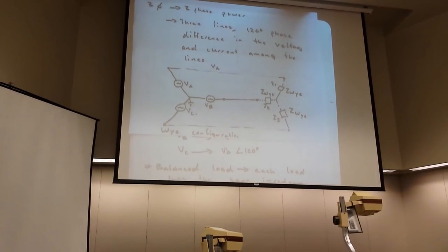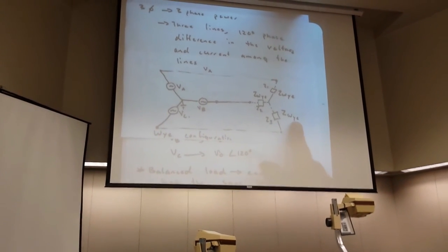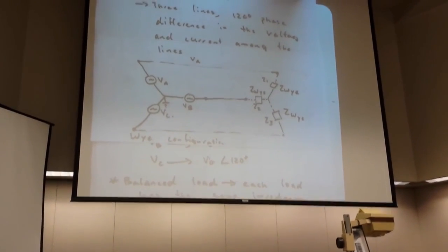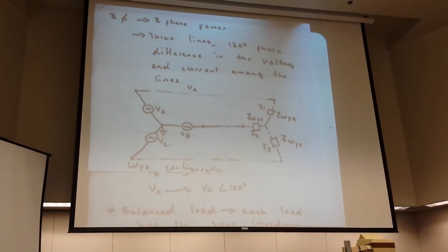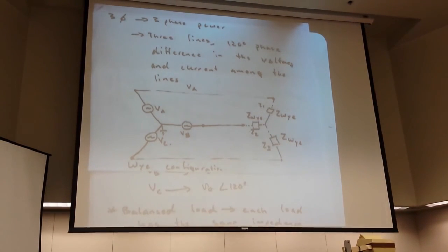How are these lines supplied? So previously we said this building may get VA, the JDC may get VB, the physics building may get VC or whatever. How do they choose, in some sense? How do they pick which loads go with which line? Well, a lot of it's based off experience. The goal here is to have these as close as possible. So you look at building usage, how power is going to be demanded as the day runs on, and you try to set these up so they're as close as possible.